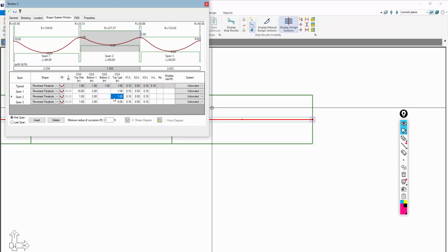And over on this side, this is 9, referencing from the top of beam here. We're going to say that's also 2 inches down. Let's say we want a little more clearance there, maybe 3 inches. And let's do 3 inches here. Okay, so that is in essence the first tendon that we're going to add.